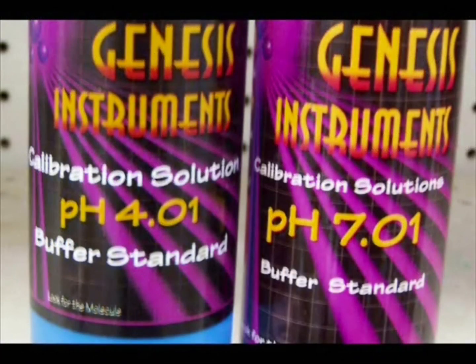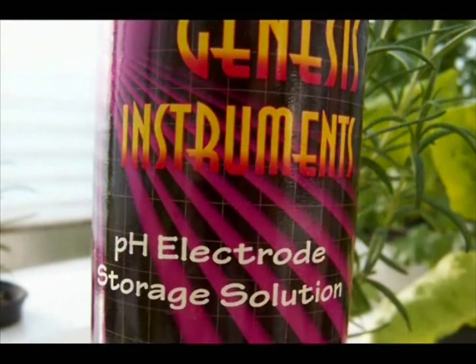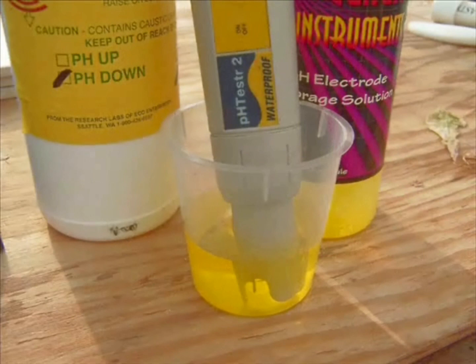pH pen calibration solutions are available to calibrate both lower and higher pH indications. pH pen accuracy should be checked often and calibrated when needed. When not in use, the pH electrode should be placed in a storage solution. This is easily accomplished by merely placing it in enough solution to cover the electrodes. If the pH pen has not been used for an extended period of time, the electrode can be reconditioned by placing in a storage solution for about an hour before using.